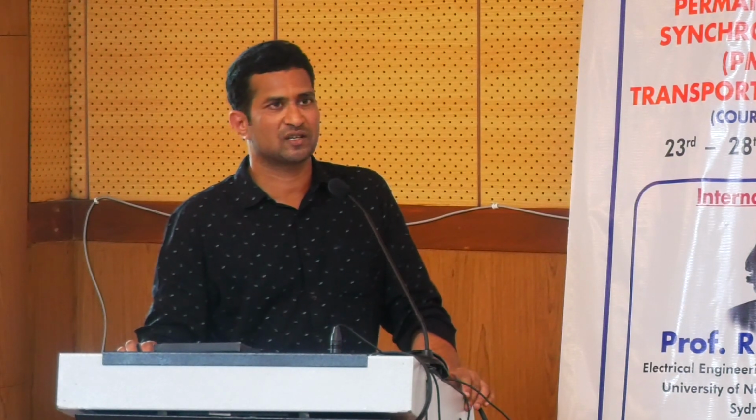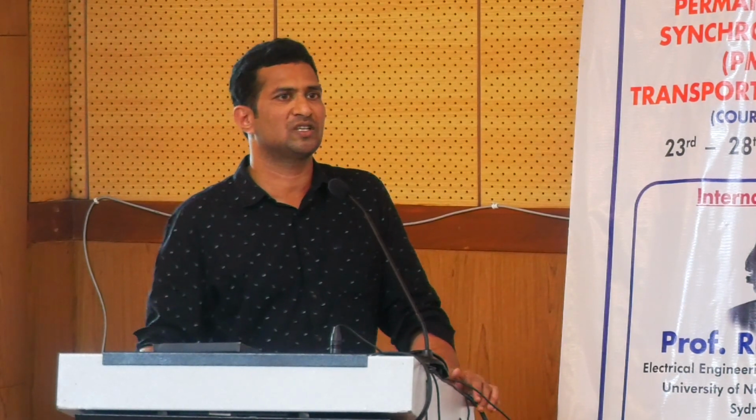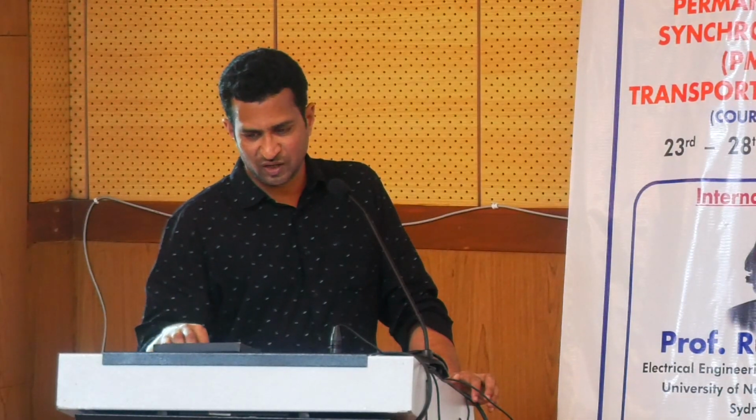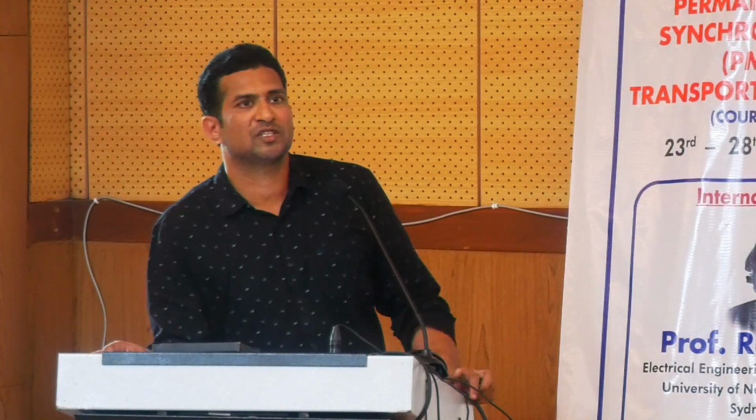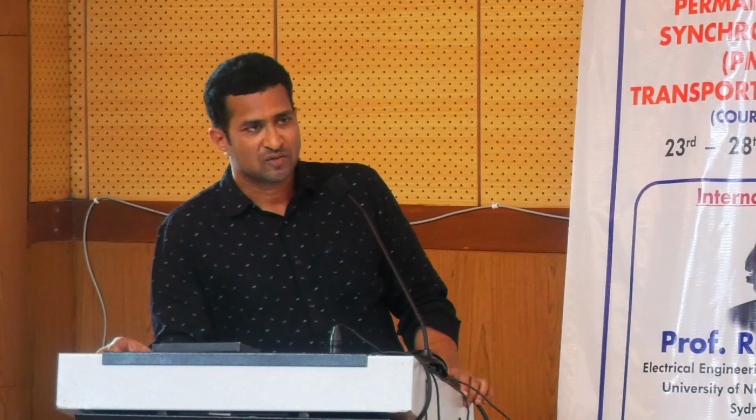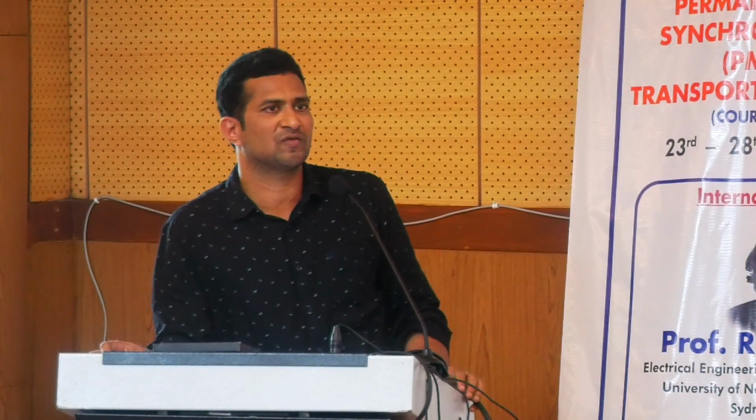Next we have the matrix converter. Matrix converters use self-commutated devices, right? Matrix converters have several drawbacks. One common drawback is frequent short circuits at the output terminals, right? That's why, compared to DC link converters, these matrix converters are less used. So we are moving to the DC link converters.